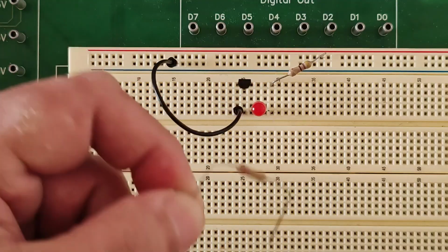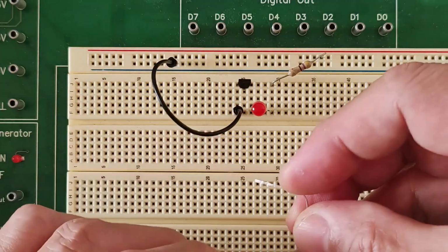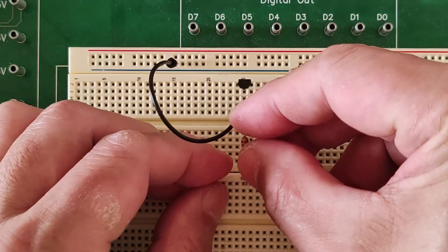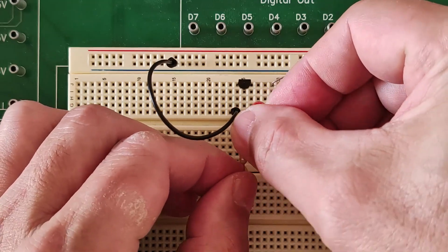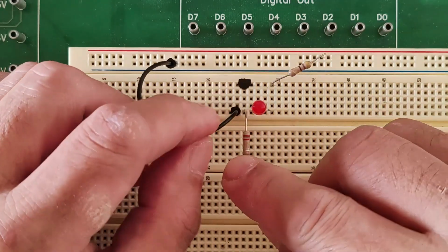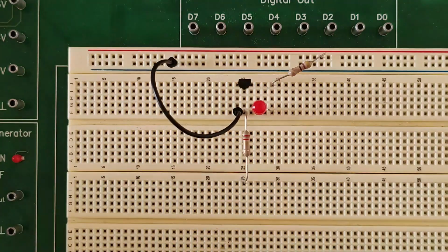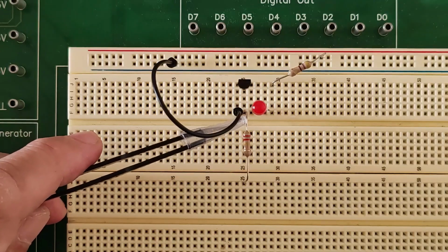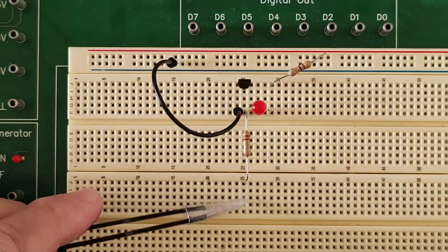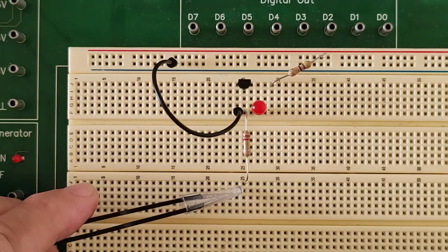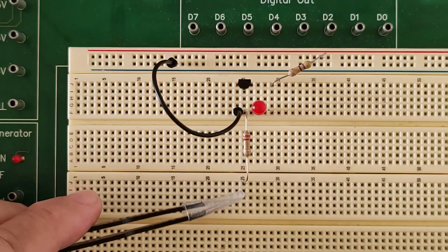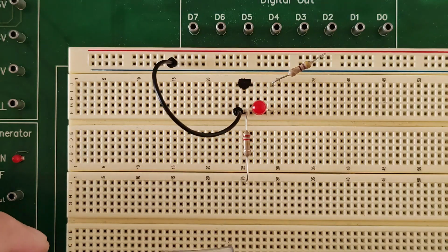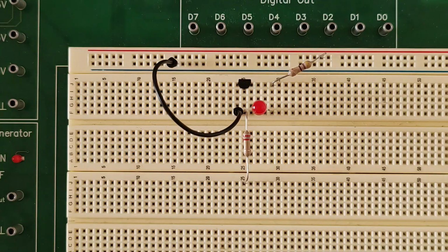For the meantime, let me just connect one of the legs to the base, and I'll connect the other leg to a free pin somewhere down. Let's do that now. One leg to the base, there, and the other to a free pin somewhere down. Push it a little, there. So this leg of the 220 kilo ohm resistor is connected to the base, and the other leg is connected to a free pin.